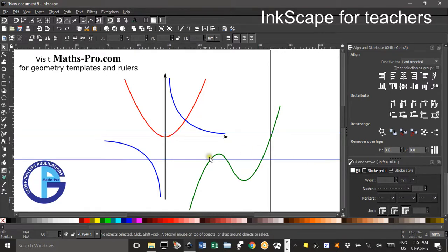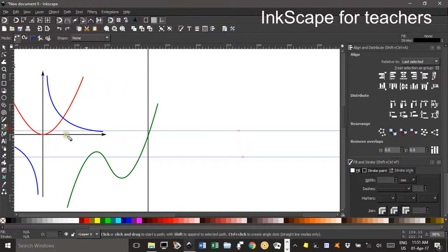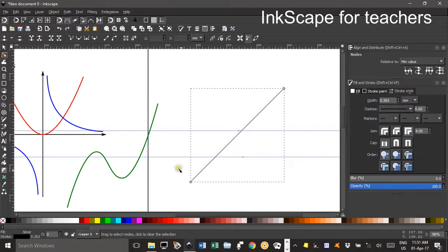Much the same way you can get points of inflection, the same way using these particular guides. If I just wanted a simple y equals x cubed graph, I could just draw a Bezier pen tool, click, Control to force 45 degrees, double click, select the nodes tool, shift click, or click the first one then shift click the second one, add a node using this button, and clicking on that,